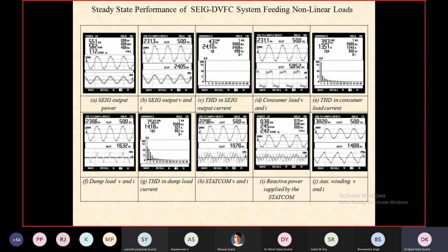In a 132 frame size, you can wind a 7.5 horsepower machine for 3-phase configuration. For 3-phase configuration, you can wind 7.5 HP in 132 frame size. But for the same frame size, if you wind a single phase induction motor, then you have to wind 5 HP only.